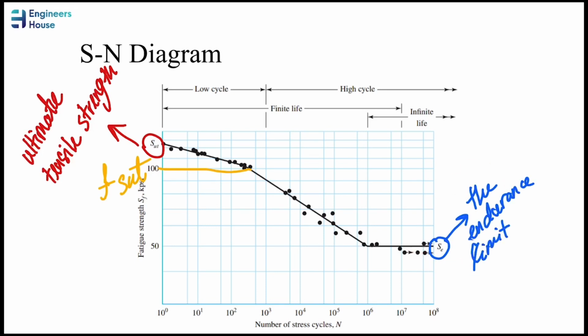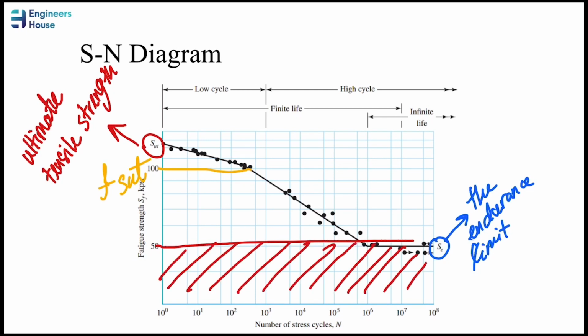The endurance limit is an essential parameter that needs to be considered in many design problems. It is quite important to know what effect this parameter has on our components. For values below this line, your machine component will have an infinite lifetime. But if you exceed this limit, you will be within this area, which is not an infinite lifetime, but a finite one.